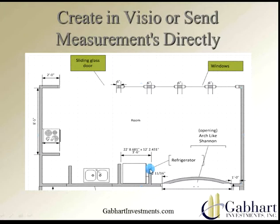If I have side panels on the refrigerator and a cabinet on top, it's probably about $400. I can build this in and make it look custom with drywall, and it'll cost me $100, $150, because I'm already doing a lot of drywall in the rest of the project. It takes somebody an hour to frame this in, and another couple hours of drywall while they're doing the rest of the work.